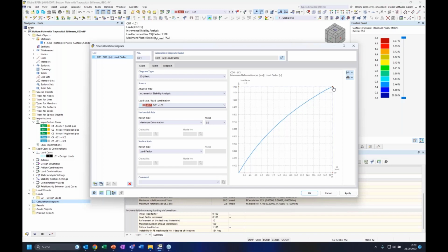For example, it could be because of the material nonlinearity, because of some bigger distortions of elements, because of some contact that I have in the model, or it could also very well be due to stability failure, because maybe at that point, somewhere in the model, a buckle evolves and there is a quick jump in deformations in a small area, and maybe also a decrease in the overall load resistance of the model due to the formation of the buckles.